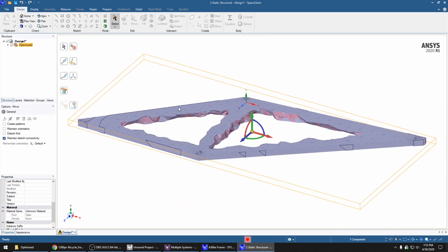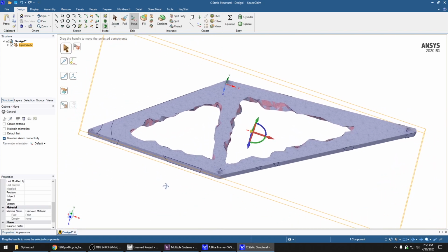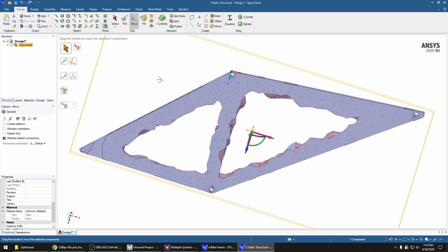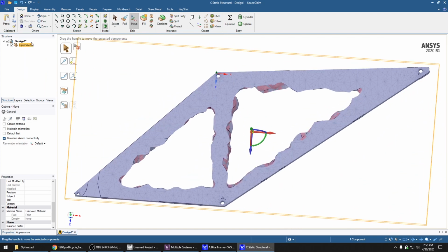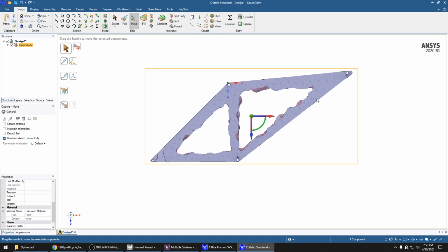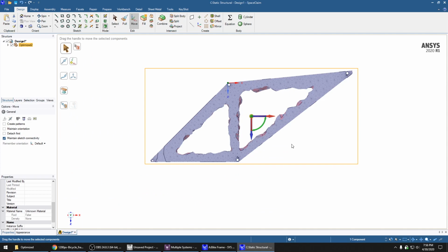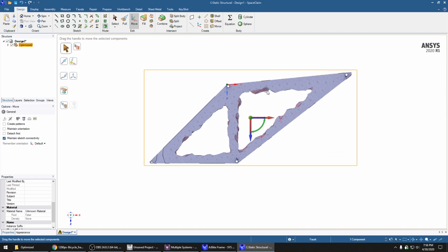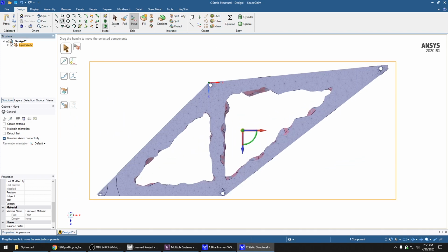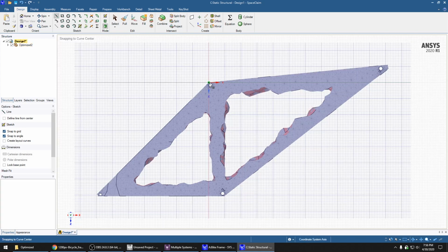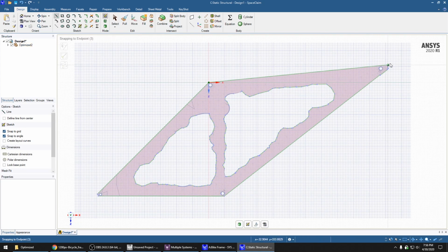Zoom out. And I kind of want to look top down. I'm going to go to top view, and there we go. So that's what we were looking at before in here, except now it's a step file. And what I'll do is go ahead and start sketching. Take the sketching tool, start at this point, like so. And I'm actually going to overshoot these corners a little bit. You notice it snaps too.